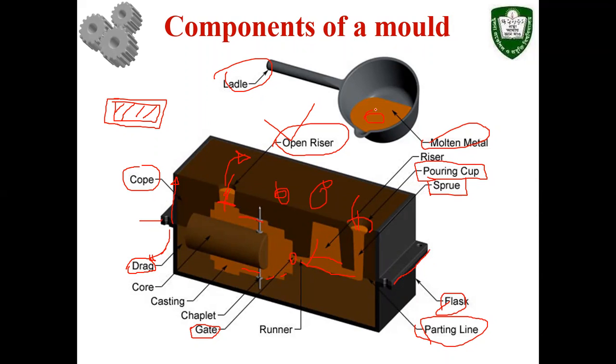Then at the melting point temperature, if the volume is V1, then above the melting point temperature the volume will be larger, right? Yes. V2 will be larger. After the cavity is completely filled up, the temperature decreases from T2, the highest temperature, to T1, where the freezing occurs, right? Yes, sir. T1 is a constant. It holds for a long time, but temperature decreases from T2 to T1. During this decrease in temperature, the volume also reduces. Volume comes from V2 to V1.